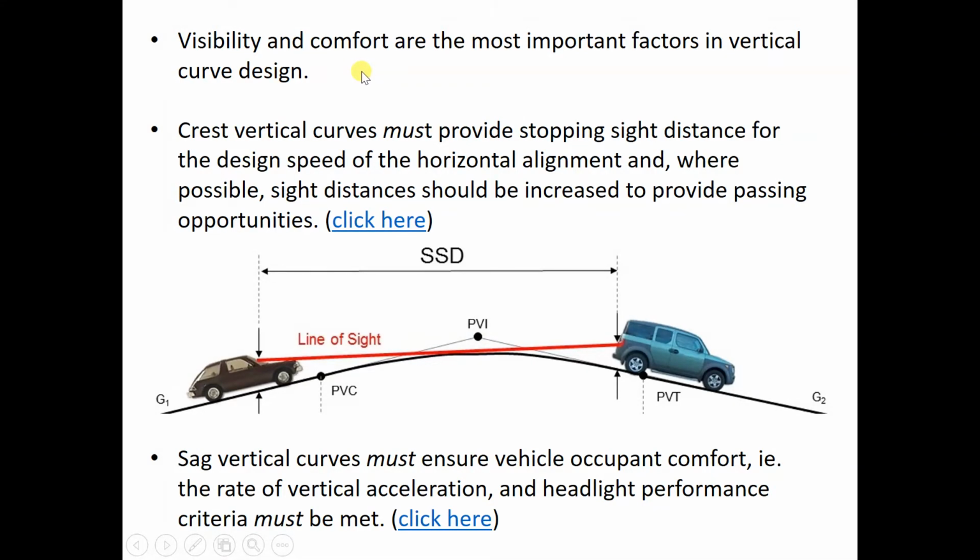So the comfort as well, especially if you have very short curves going uphill, short curve length, and then the change of direction is so fast, it's not gradual. It's a very rapid change, you go up and go down, or you go down the valley and going up. If the vertical curve length is too short, the change is too abrupt. That could be very uncomfortable, and people may experience motion sickness and throw up.